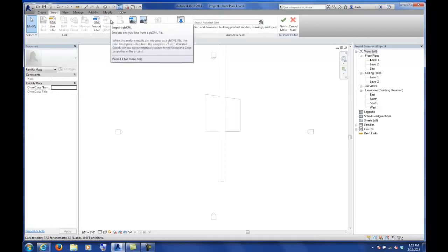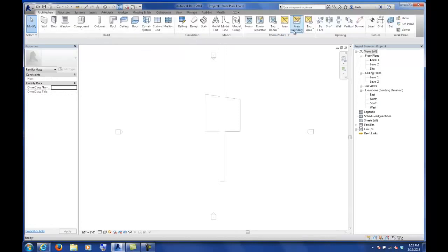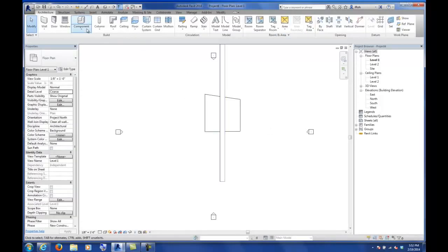That's because once you go into this mode, you're actually going into a massing family that's built into the project environment. So what I like to do is actually model in the massing family and then eventually bring those masses into the project environment, because we can then place them as objects and then work with them a little bit easier.